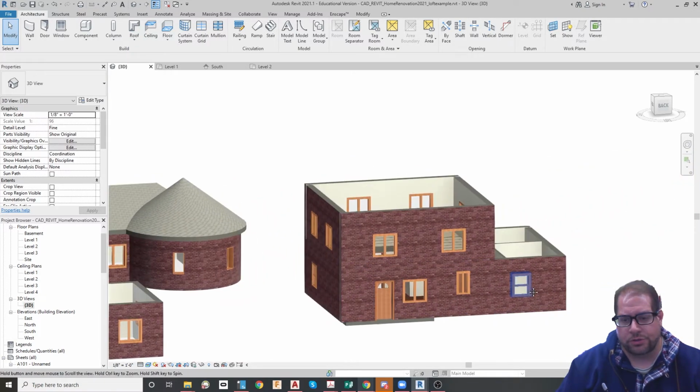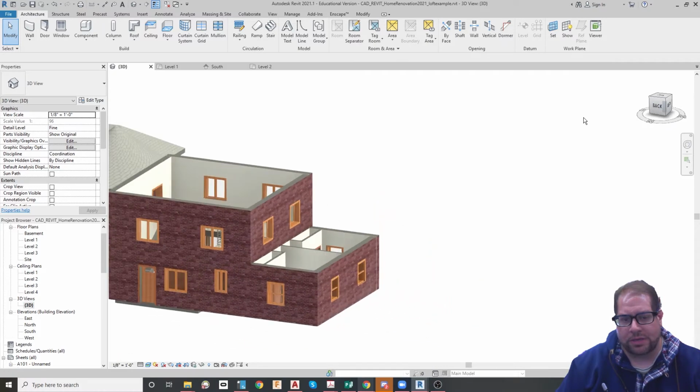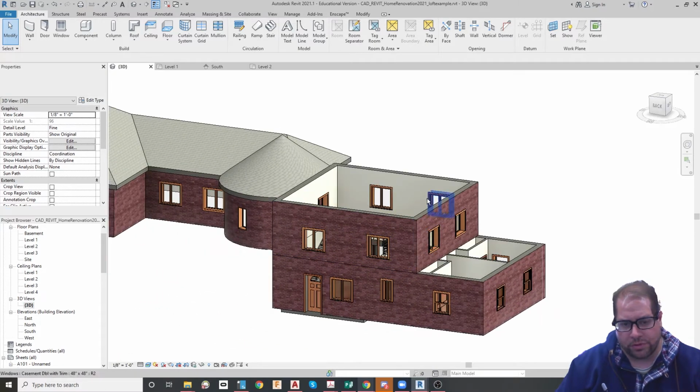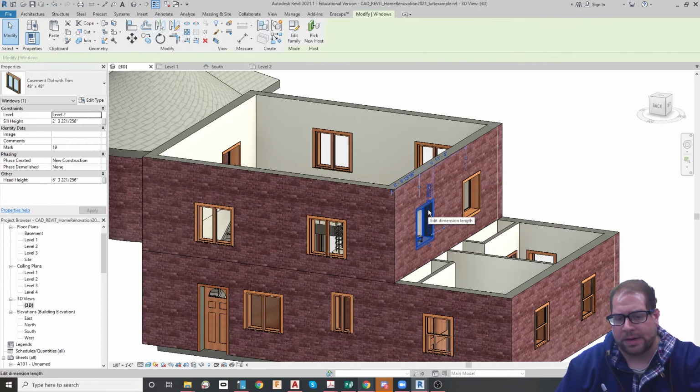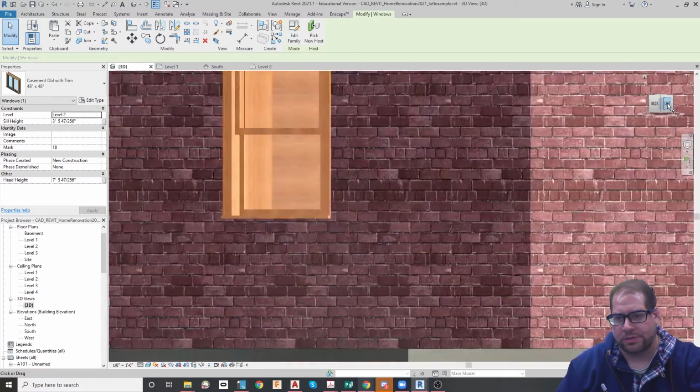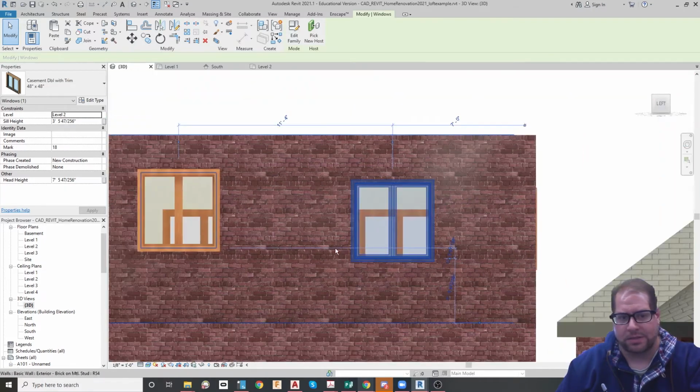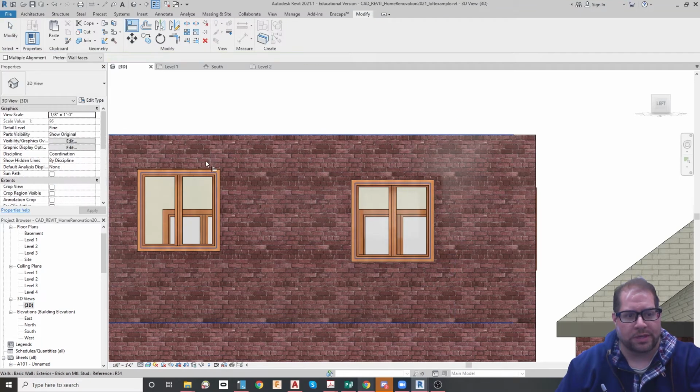Next, let's go to our 2-story home. This one is going to be a little awkward because I'm going to put a footprint roof up here and then an extrusion roof over here. And that's because of the way these windows are. To prepare for that, I'm probably going to raise these windows up a little bit. Okay, so raise them up and make sure they're the same level by looking at that side. Use the align command.